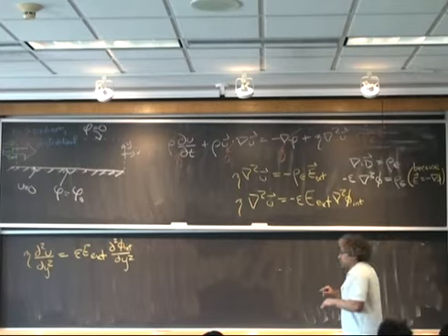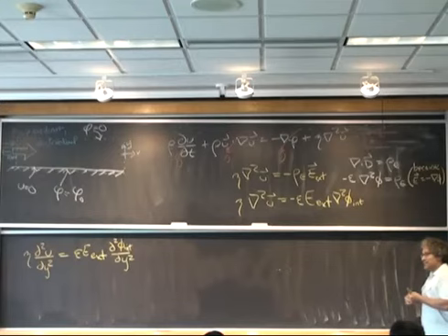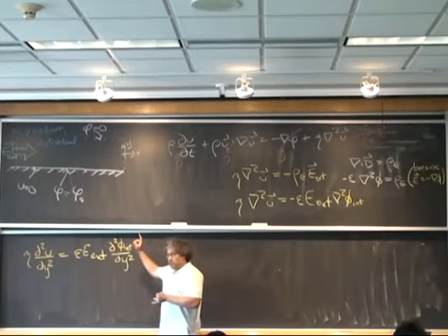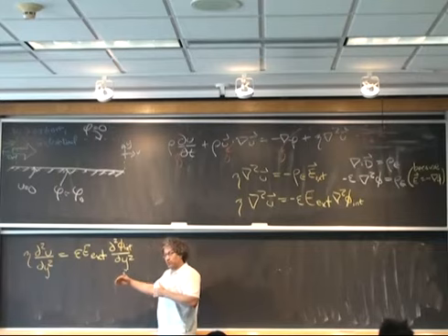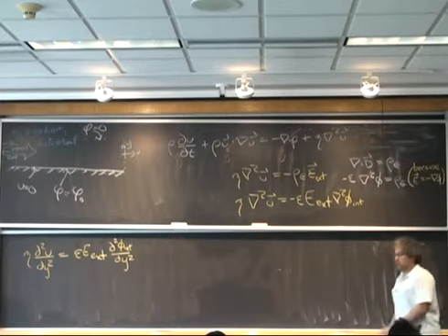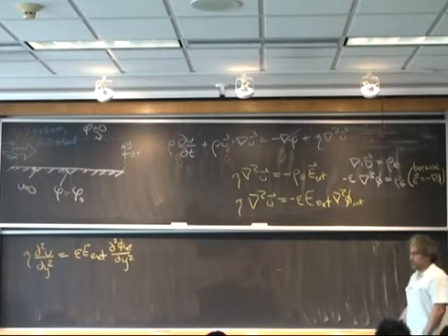The problem with the y part, one, it doesn't drive the fluid flow at all. And the other thing is, to get anything meaningful about it, I have to solve for the spatial distribution of charge in the electrical double layer. Here, I don't need to know that yet. Here, I actually get the answer I want with a strictly integral boundary layer analysis. All I need to know are the boundary conditions, not the distribution of the potential. So you definitely can do it in the y direction. You get interesting and good stuff. But we're not quite ready for it yet, and it doesn't tell us about flow. It tells us about static pressure.